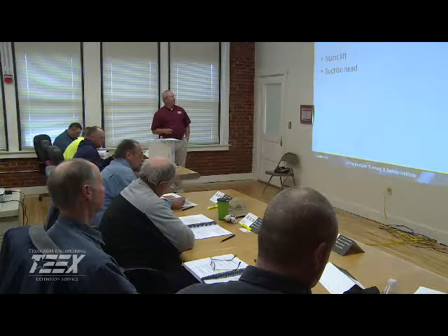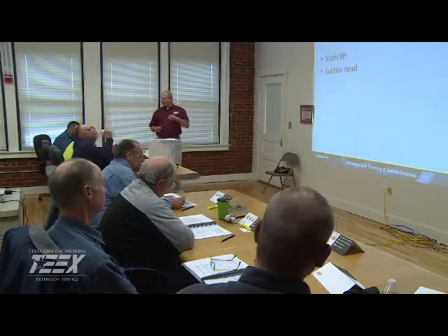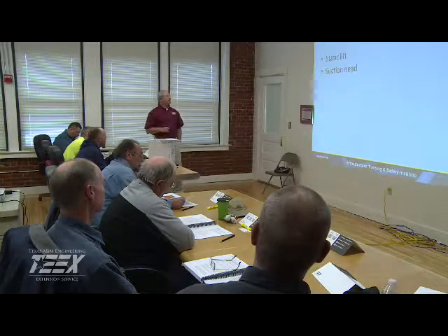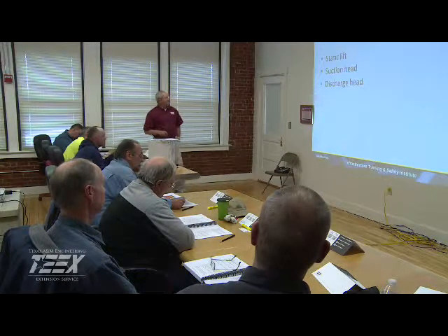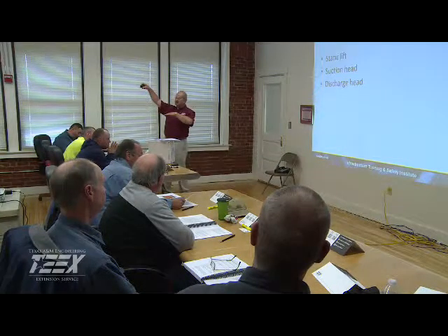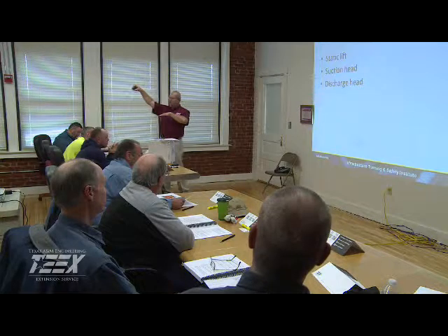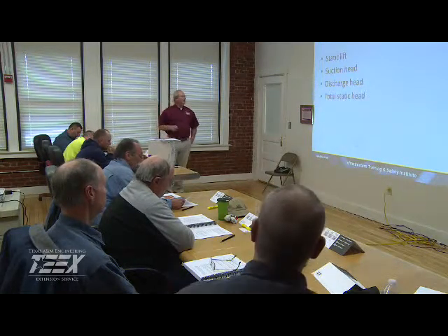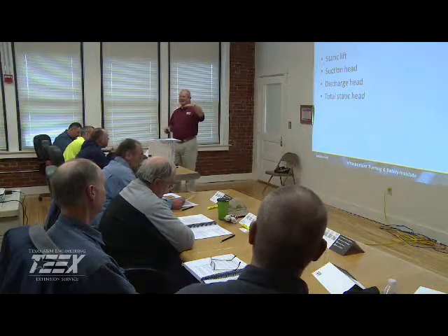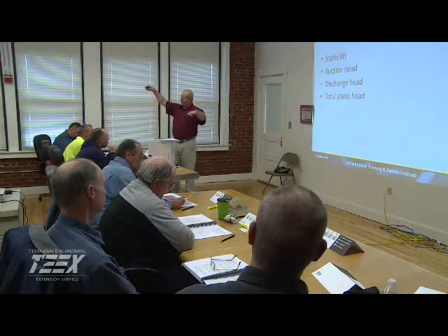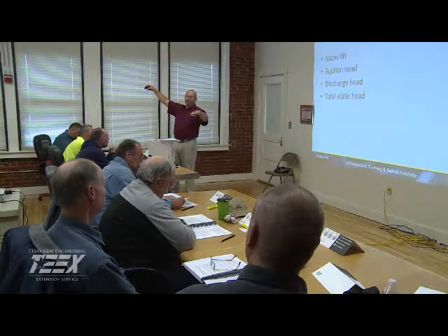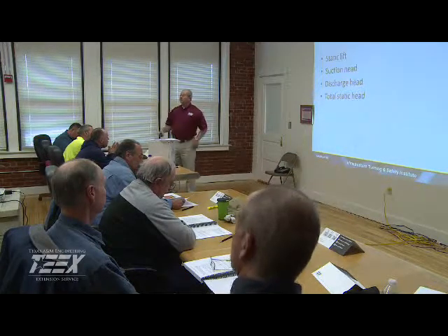Suction head is positive head. Remember, the water on the suction side is above the center line of the pump. And discharge head is from the center line of the pump to the highest maximum elevation. Okay? That's discharge head. And then we have total static head. We go from the top of the water on the supply side to the top of the water at the highest elevation. It could be less than or more than discharge head, depending on your system.